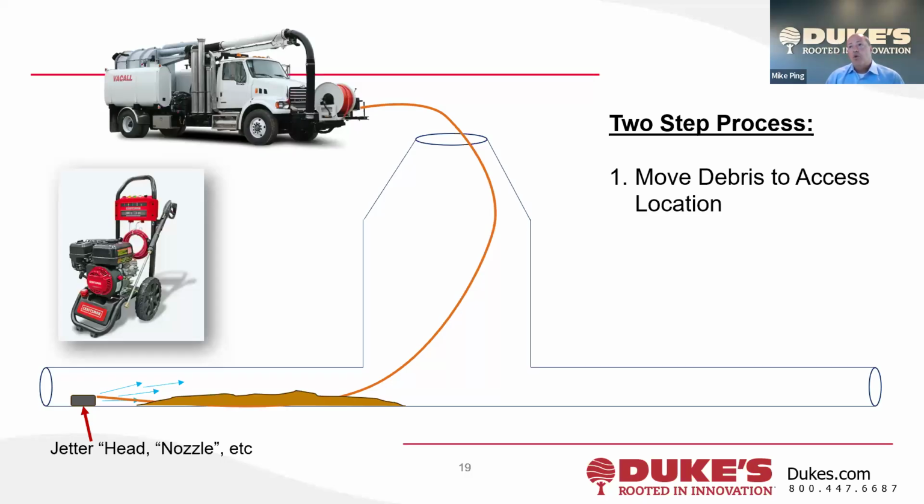So the way that this works is this hose gets deployed into the manhole. You can see that the jetting action is going kind of backwards compared with a pressure washer, right? It's going back towards the hose, right? And that has enough force generated from the jetting to pull itself out. And as I said, typically it's going to go to the next manhole.